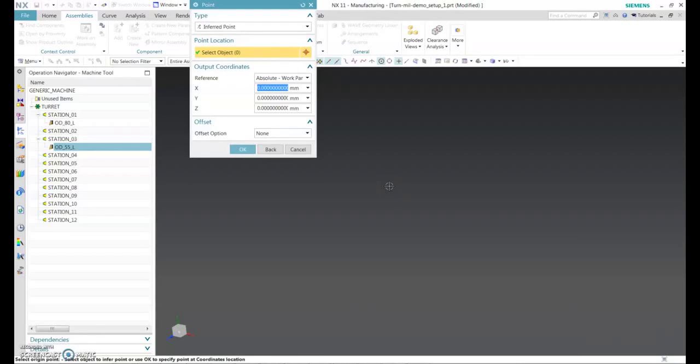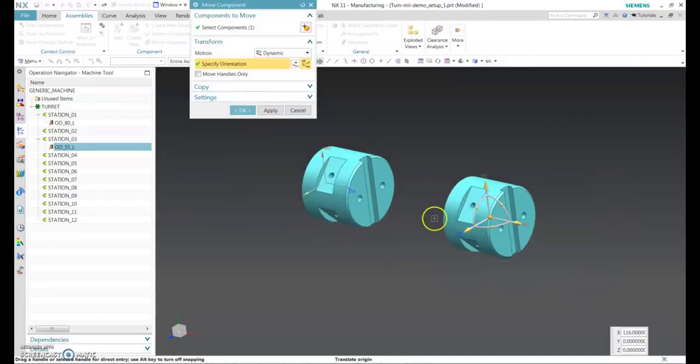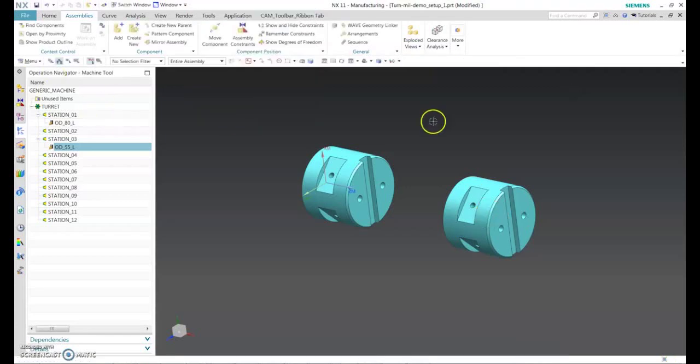So what you want to do is you need the sub-spindle part to stay away 100 millimeter from the main part. So now you got the sub-spindle part to put in the sub-spindle define. Your sub-spindle in your machine tool is more than 100 millimeters away from the main face of the main spindle, right? You can move it as per you want. It can be 300 millimeter, 500 millimeter, or 150 millimeter. So find out the length between the main and sub-spindle. Hit OK.